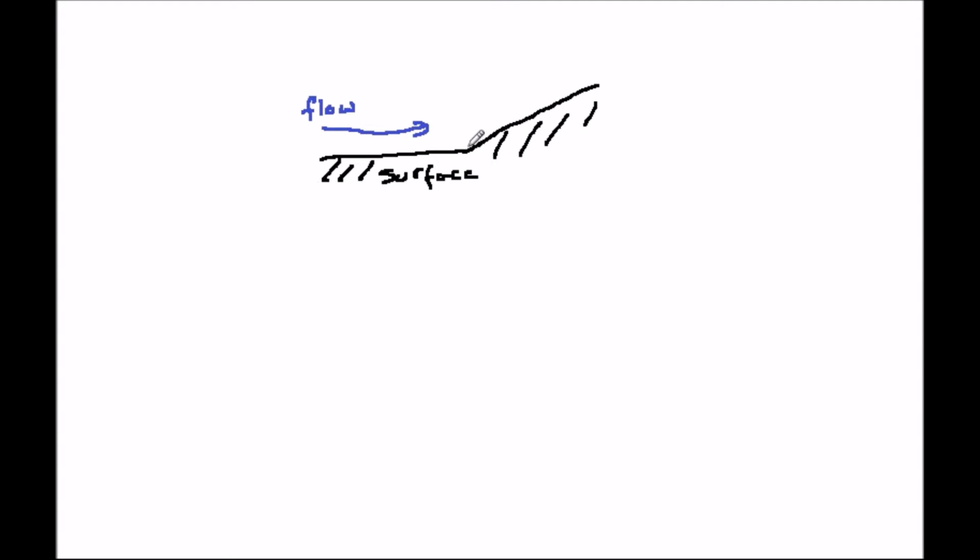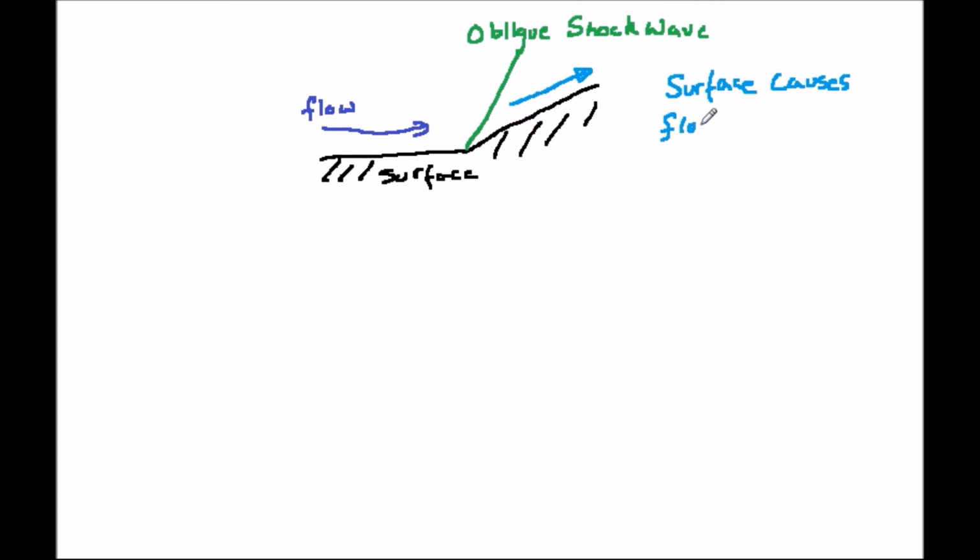The other type of shock wave which occurs is called an oblique shock. This happens when a surface turns into the flow, causing it to compress. We should note that if we try and turn the flow by too much of an angle, the shock wave will become detached, as we've just described for normal shocks. The flow after an oblique shock may be subsonic or supersonic, but in our case, when we're discussing ramjets, will normally be supersonic. The other variables show a behaviour similar to that of a normal shock wave.